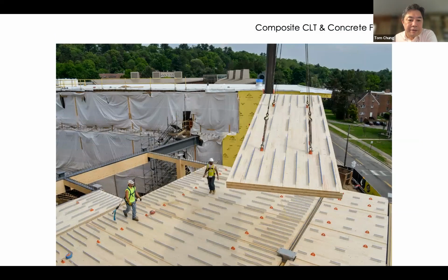And overall, as the construction was happening, it was really indicative of the speed of construction and the small number of workers necessary that is typical in a mass timber building. You need a crane operator, a person organizing and coordinating, and a small crew of typically about 5 to 7 people receiving these panels, screwing them into place, and doing the overall frame installation.